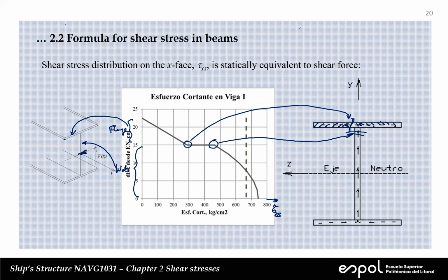If you make this plot with shear flow instead of shear stress, this value here will be twice this value here, because on one side you consider only this flange.